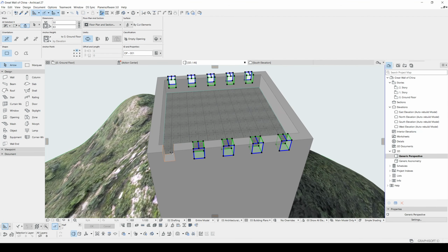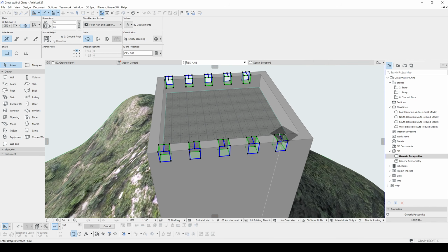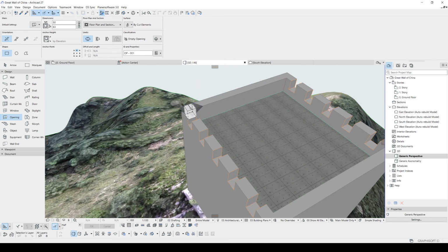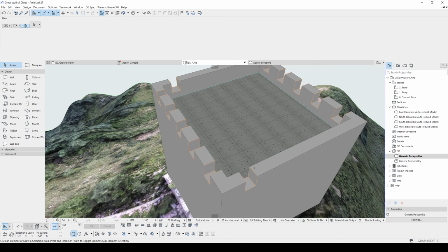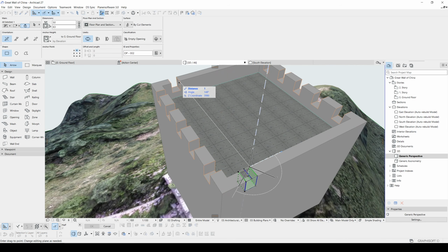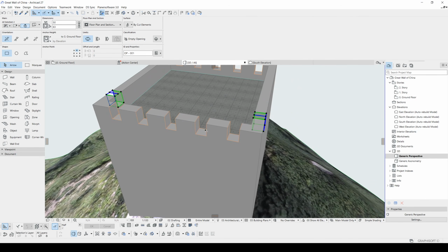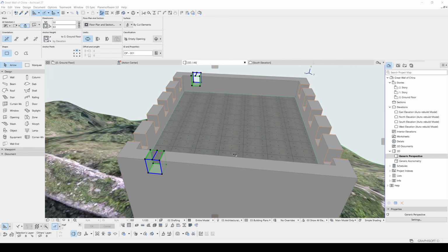Let's select all and adjust the openings. We will move these to the center. You can see this 78. We will divide this too. Now we are going to do the same for the other walls. Same steps as before. We are going to duplicate these openings to the next and select both. The distance between them, 140 is okay. Now we can multiply just as before.